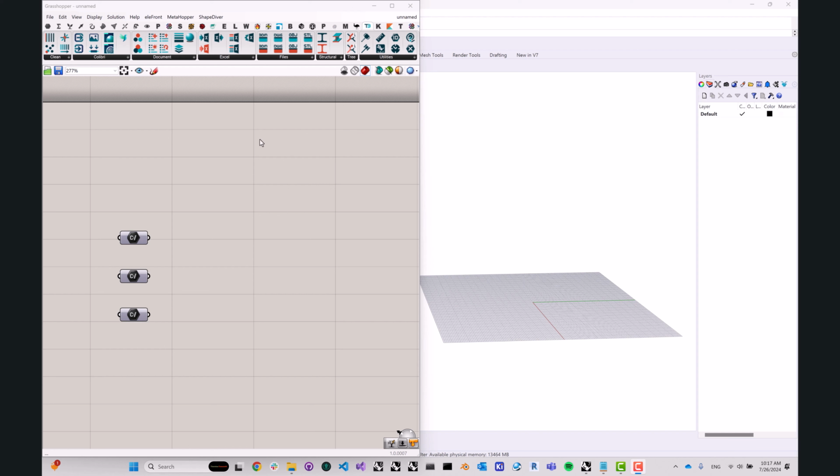TT Toolbox, however, takes it a step further and brings this import-export functionality directly into Grasshopper, allowing you to jump across CAD formats parametrically. So if we take a look at this Files tab in the TT Toolbox Grasshopper menu, then you'll see a number of components corresponding to a number of different formats. So we have 3DM, CAD, OBJ, STL, and SVG. And you'll also notice that we have two colors for each of those formats. So the turquoise component is for exporting your model to a certain format.